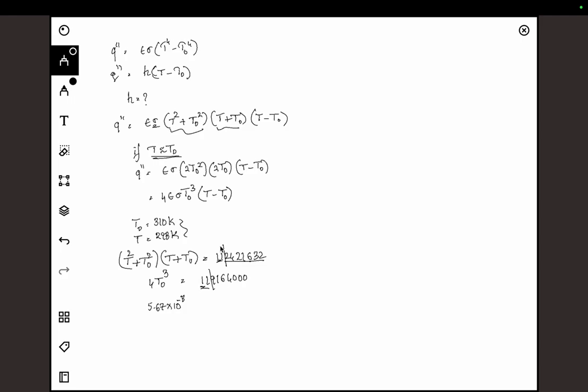But obviously when you have a hot furnace or something where the temperature itself is 500 Celsius or so, then it will be like 700 Kelvin and 300 Kelvin. That difference is too huge, and this assumption will not be valid. So only under moderate conditions, like 30-40 Celsius scenarios, this particular approximation is valid, and we can still use this relation. So even though we cannot use this fourth order power, we can simply replace it with this particular one.